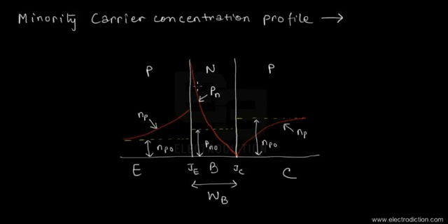And this gradually comes down as one goes towards the collector junction over here. Now since this junction is reverse biased, that's why the concentration drops over here. Due to the reverse bias, the hole current components that come from the emitter near the collector junction are quickly drawn away from this junction, and they increase in concentration, as you can see, as one goes deeper into the collector section towards the collector terminal, as you can see over here.